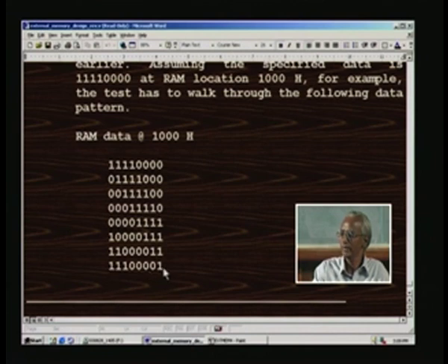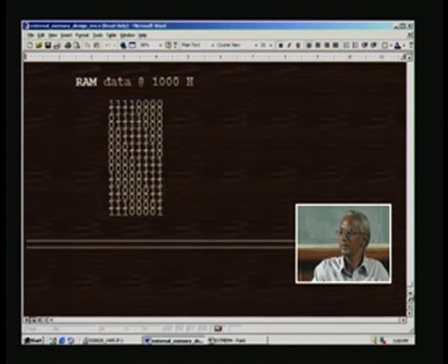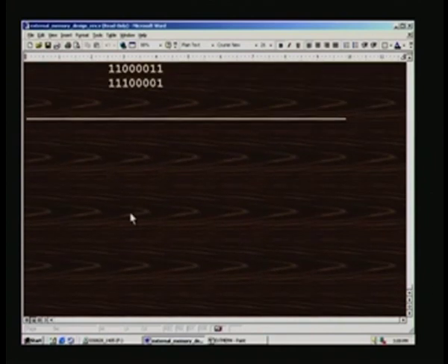So, when you come to the last one, when you rotate, this one will go to 1, which will be the same pattern as we started with before. Therefore, we do not test that condition again. So, you just exhaust all possibilities here. Being 8 bit, you need only 8 such writes. After this writing, when all are successfully written and checked back, you report pass, and this ends the memory design, and thank you.